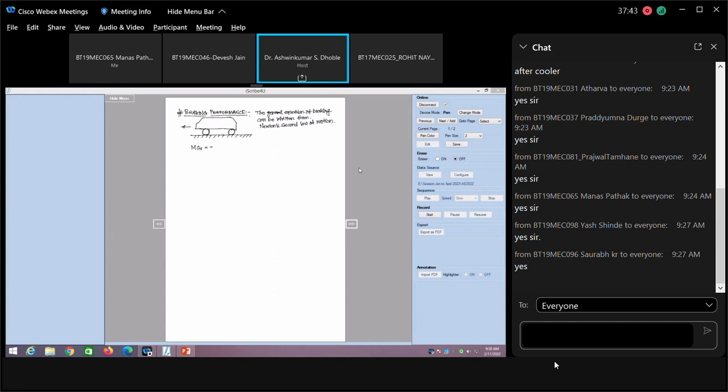This is given as minus W by g into dx, that is the deceleration, because when you apply the force, so that has to be equal to minus Fxf minus Fxr. That means the front axle braking, rear axle braking minus aerodynamic drag minus W sine of theta. So this is the general equation. I will write down the meaning of each and every term in this particular equation.